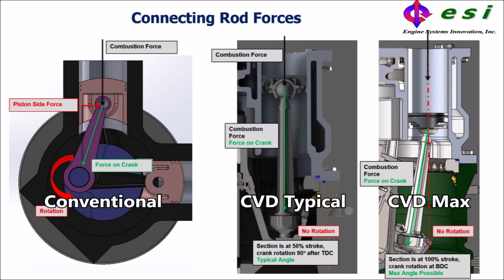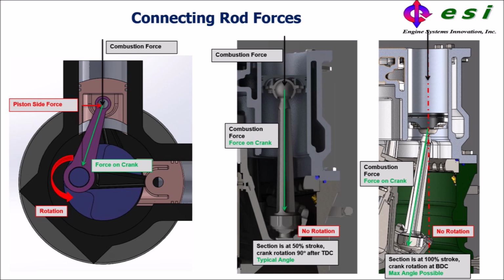The big end of the rod does not rotate about a crank pin, but barely moves as it connects to a nutator. The little end of the rod has even less movement, as the rod is almost always parallel with the cylinder, as can be seen in this cutaway.